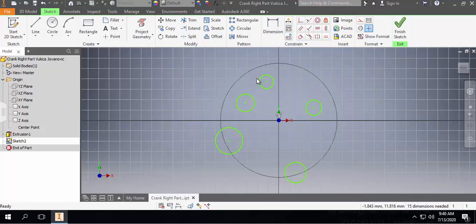So I'm saying escape now, and look, I'm trying to move. If I'm holding the center of my circles, you see I can move them anywhere pretty much. So I don't need 5, I can delete one of them. You see their location is not defined. We need to define the x and y. In this case we have x and y, so we need somehow to either use a Cartesian coordinate system or use polar coordinate system. So one way to constrain the circle is to say, okay, I need my, either, if you know, you may use the polar coordinates.